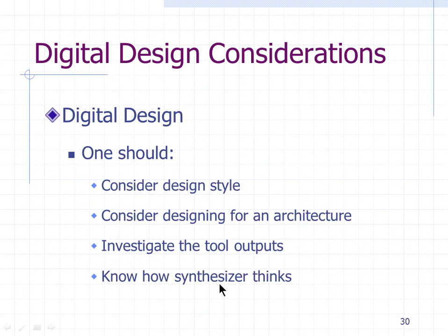Know how a synthesizer thinks or works. Synthesis is a very critical part of this entire flow, which will convert your Verilog code to netlist format. Depending on how you define your Verilog code or Verilog design, the synthesis tool will automatically convert that to a netlist. So you have to understand that when you write something in Verilog, what will be generated in hardware, because that's what the synthesis tool will do for you.